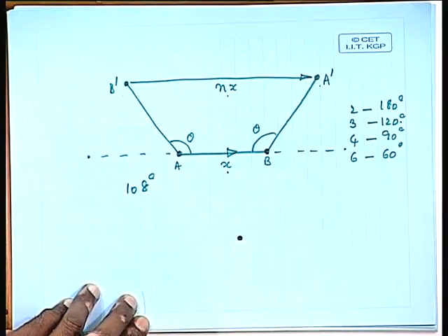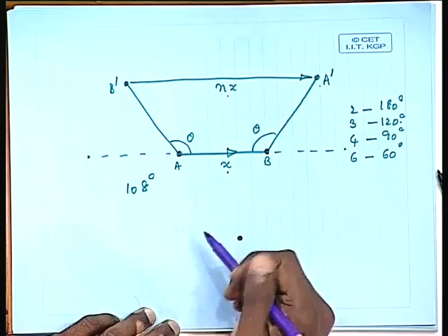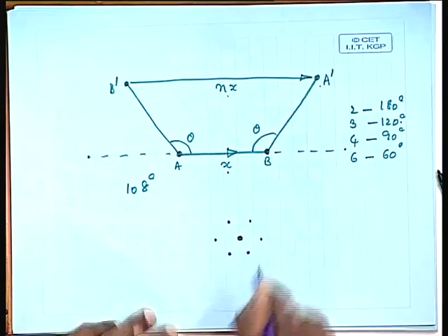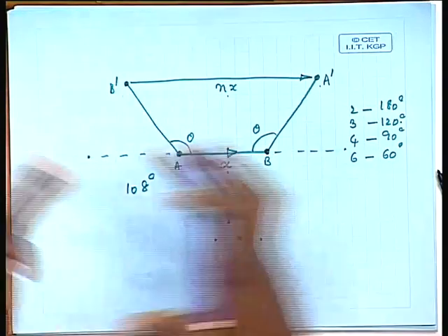Let us say I have put a sample in a TEM and then oriented my sample in such a way that the 111 plane is now perpendicular to the electron beam. Now when the electron beam is coming through the sample, it comes across the 111 plane and tries to see what is the symmetry of atoms around that plane, and the diffracted beams that you get, look at the diffracted beams, and what you see is a transmitted spot like that and diffraction spots which look like this, and so on.